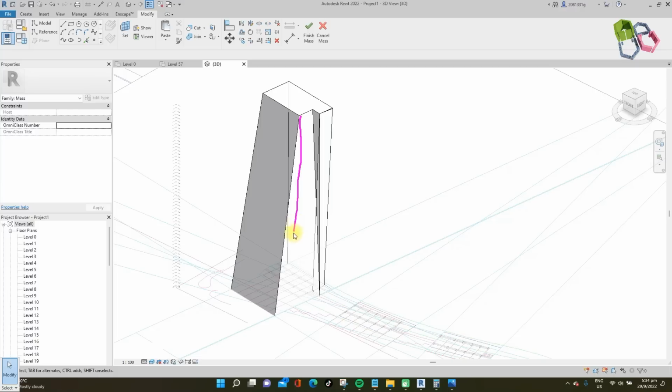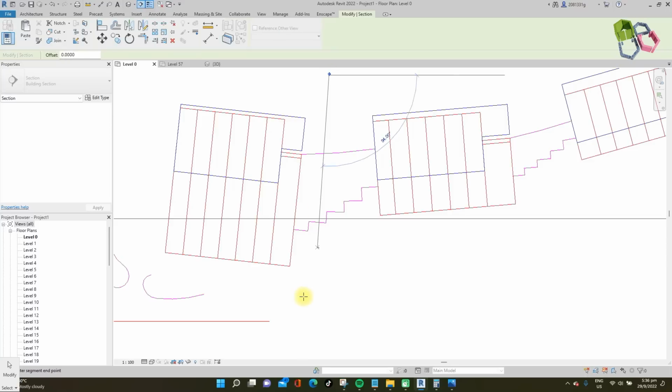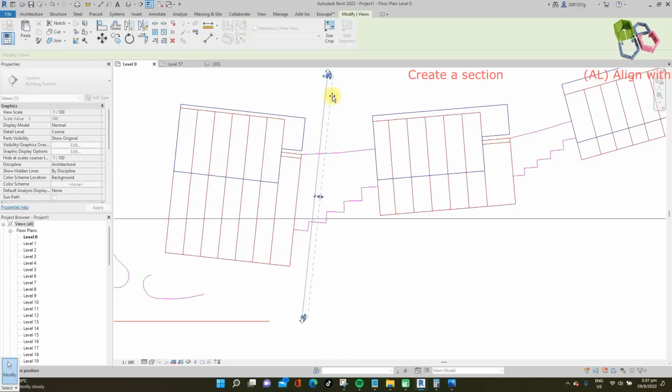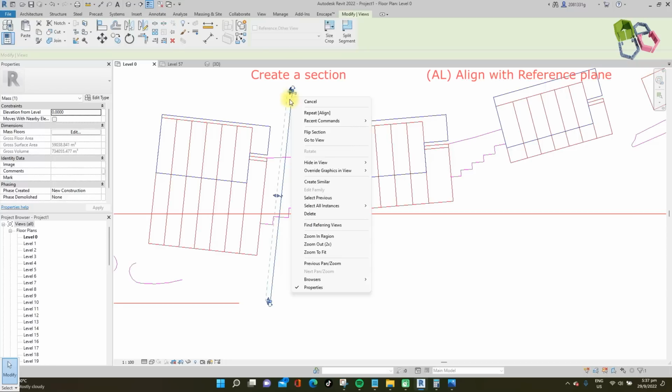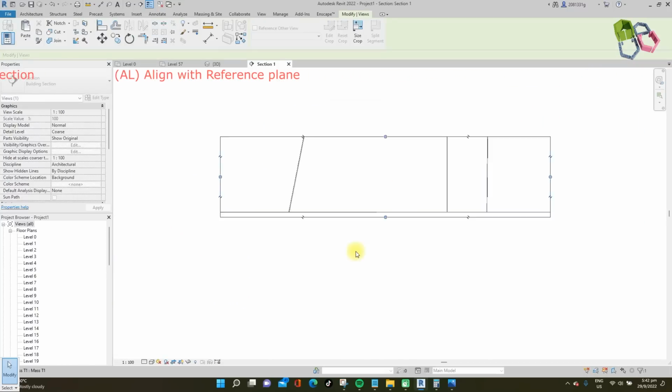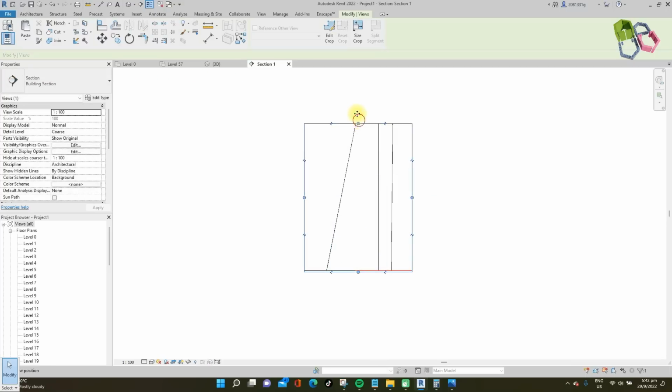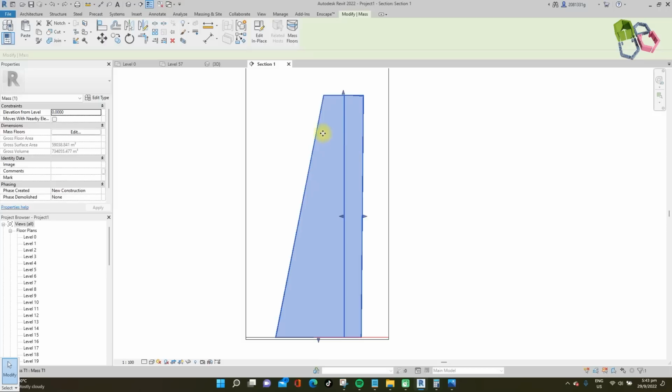Okay, this time I need to cut the curve-shaped mass form. And I need to place a section here, aligned to the Tower 1 surface and brought back a bit. This will be the Tower 1 mass elevation. And select the mass and edit the mass.